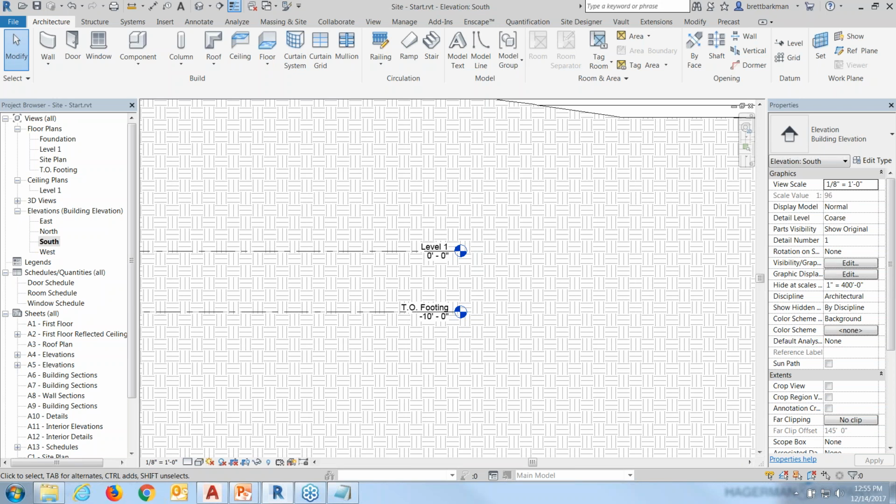From Steve: Is there a way to extract actual 2D contour lines instead of just the text points? Yes, and that was the third example that I did. That was in 3D, however, but you link in your CAD file, just like we did, and then build your topo surface based off of the layers that the contour lines are on from the CAD file. So great question.